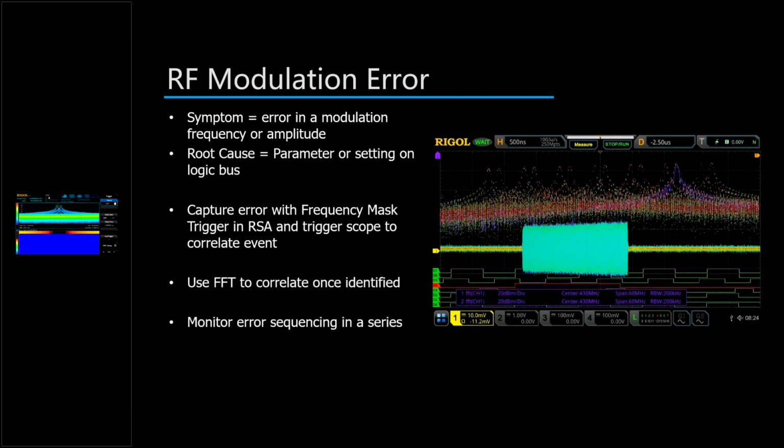If you've been watching, you can notice a couple things here. One, we can see a little wider on the IF output than we can on the front of the analyzer. So we can see the pairs that were off the screen a little bit on our analyzer, and we can clearly see the signal is working in 7 different channels with an FSK modulation within each of those channel patterns. That allows us to verify the power levels and timing of each pulse, regardless of where it ends up in the spectrum, and debug it that way.